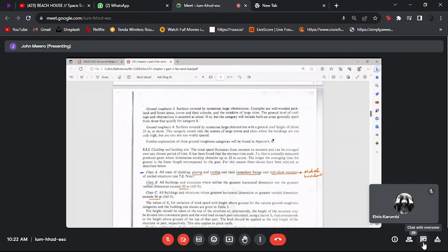As the building becomes bigger, the maximum possible average wind speed becomes lower because of the averaging effect. As the building becomes smaller, the maximum possible wind velocity becomes higher, and as it becomes smaller, this concept goes all the way to be applied to fittings. Okay, so cladding, glazing, roofing, intermediate fixings, etc.